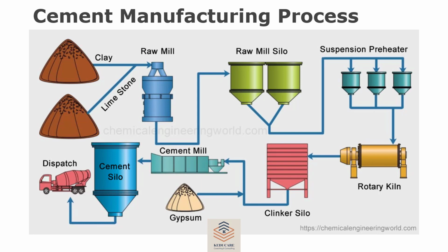Once this part is complete, the main part of the cement manufacture is complete, and it is put into the grinding section, which grinds those small balls of stone into dust, the very small powdery thing that we see in cement bags.